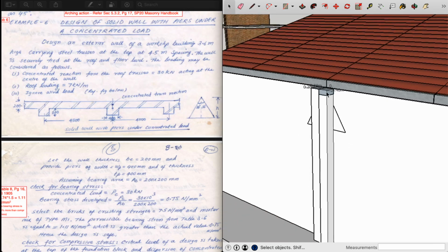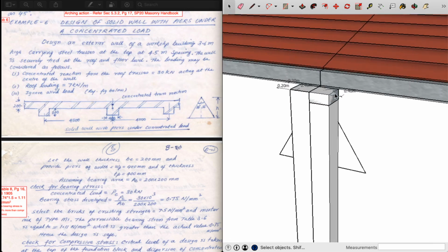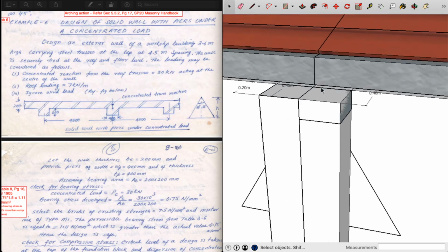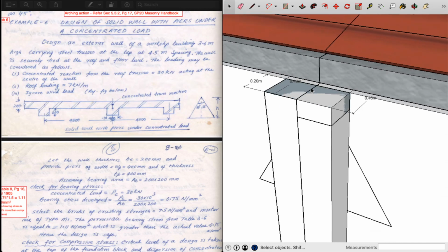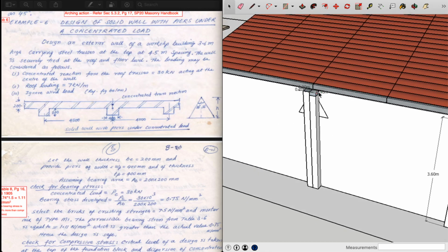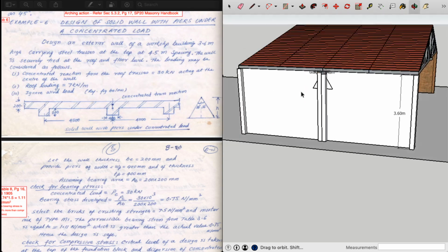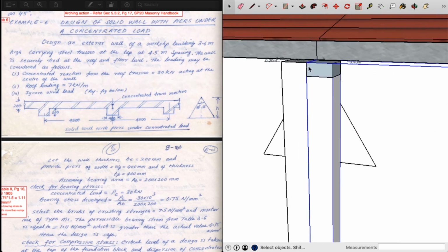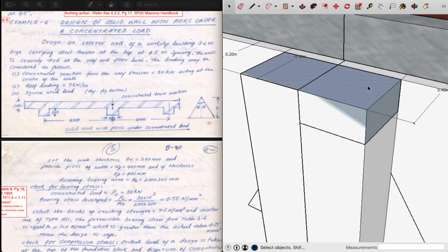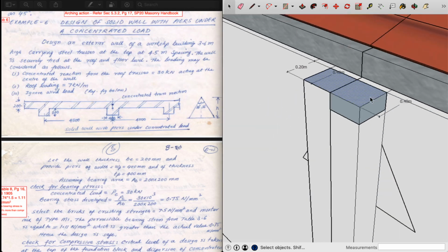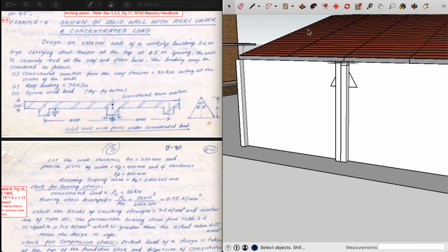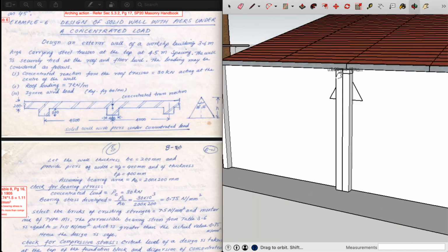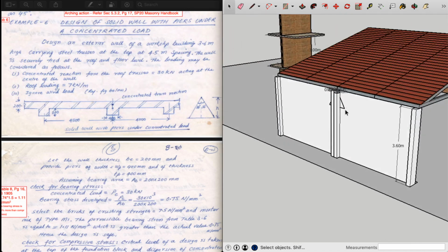concentrated loads. Now, the thing about point loads or concentrated loads is that when they act upon a particular point in a masonry structure, they exhibit a lot of local stresses. There is a stress happening all the way through the entire wall, but then there is a local bearing stress acting upon that particular masonry structure. Now we need to make sure it is safe against any such extra stresses that are developed due to that particular point load.